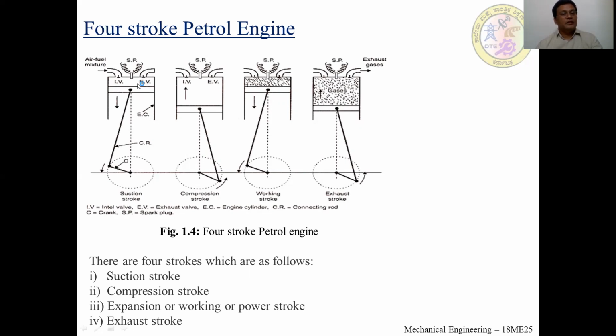During this stroke, the piston moves from TDC to BDC, and with respect to valves, the inlet valve is open and the exhaust valve is closed. When the piston reaches the BDC, the suction stroke is completed. Then the second stroke, that is the compression stroke.